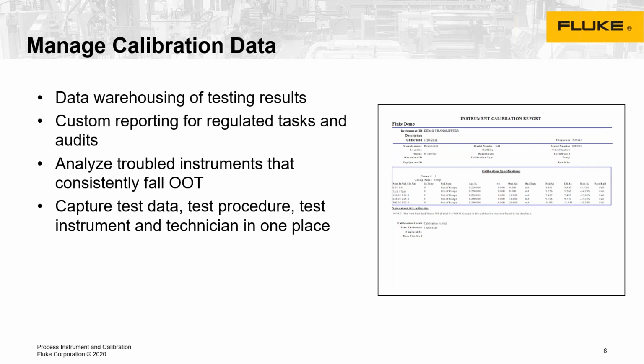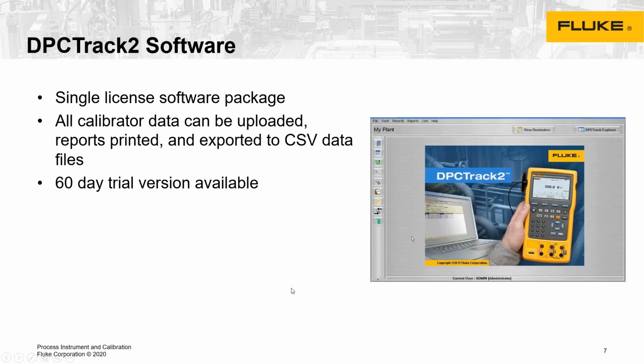You can add supplemental data to it, like operating conditions, checklisting features, visual inspection information, and then produce reporting, which is an example on screen of a standard instrument calibration report, providing the as found, as left data with the pass or fail and standard deviation within those tests.